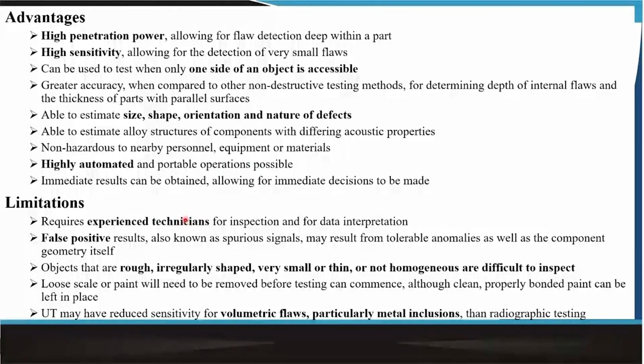The limitations are that an experienced technician is required for data interpretation. Sometimes false results occur. So, you have to know, for which situation or case, how the wave or signal will look. Objects that are rough or irregularly shaped are difficult to inspect. Loose scales, like oxide scale, if present on the surface,